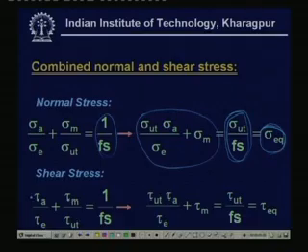By the same logic, if we write down that expression for the shear stress, we get tau ultimate by factor of safety, and a situation like tau equivalent. So, let us see what we can do with this sigma equivalent and tau equivalent.